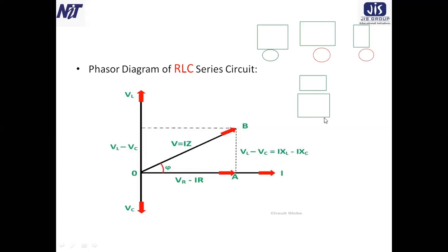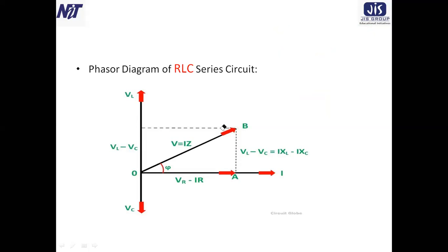Now, let me show you how to draw a phasor diagram of the RLC circuit. In the same way, we are considering I as our reference phasor along the x-axis. For VL and VC, here we consider that VL is greater than VC.